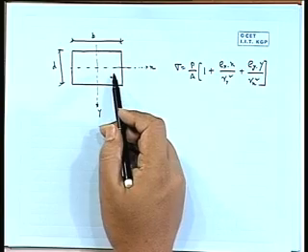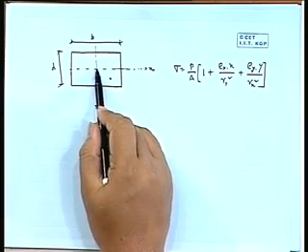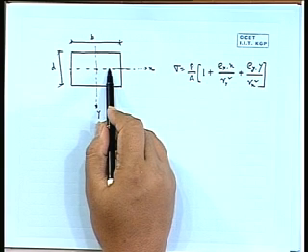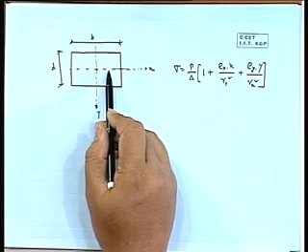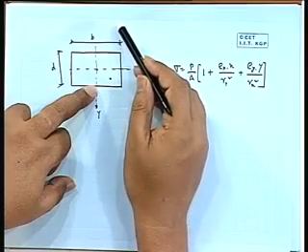Okay. Now, earlier we have seen if the load is at b by 6, so here the limiting line was passing along the outside line, and if it was here, it was along this line. Now if it is here, it will be some line, there it will be 0. If the load is acting here, say at b by 6, then your 0 stress line will be here. If it is beyond that, it will be inside. Now if we take this side as d by 6, so the 0 line will be here. If it is more than that, it will be here. After that, tension will be generating.